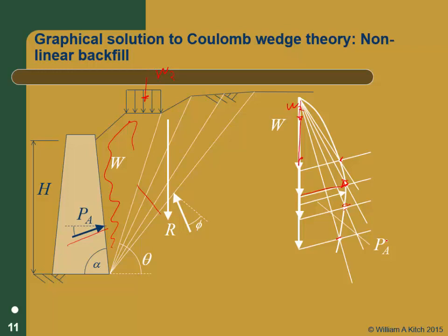And we'll talk about this later as a graphical way to calculate loads from induced stresses too. Now, we don't do graphical solutions too much anymore because they're time consuming compared to running some kind of a computer program to do this. But this is a really convenient method, and sometimes some people call this a trial wedge method. What you're really doing is just a graphical solution to Coulomb's method. And all you're doing is summing forces in the x and y direction equal to 0, and you're doing that implicitly with your little triangle here.